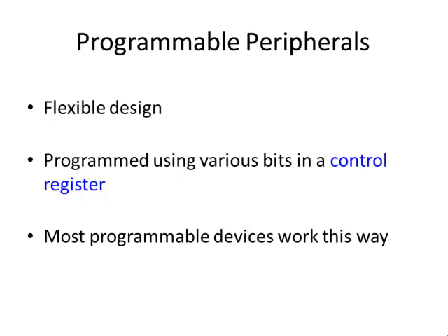Microcontrollers, as we know, have a great deal of flexibility. These timers can be configured in a lot of ways for different applications. In order to configure them, you program them by writing to a control register. Now, if you saw my lesson on analog to digital converters, you already know about programming control registers. The PIC timers have a control register for each timer, and each register has certain bits that do a particular function.